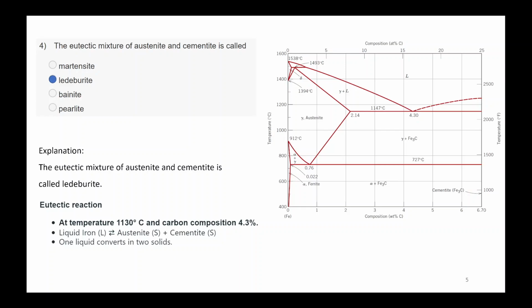But in order to form the martensite, it should be crossing that first C curve, isn't it? No. If it is going into the C curve, along your cooling curve, then it will be forming pearlite or bainite. If it is going directly without touching those curves, then it will be forming 100% martensite, or it will also be forming some retained austenite. It won't be forming 100% martensite in that case.